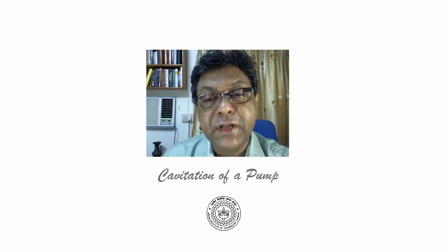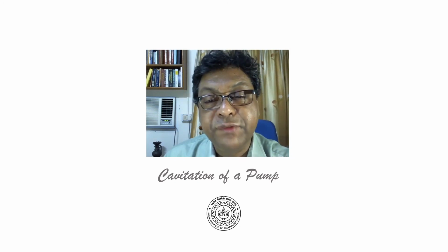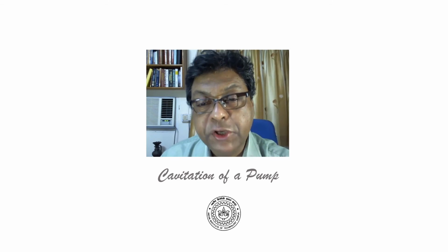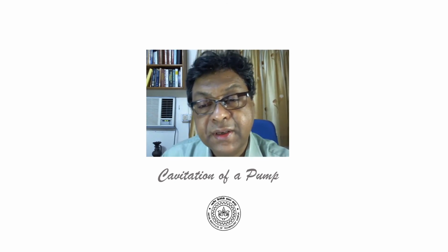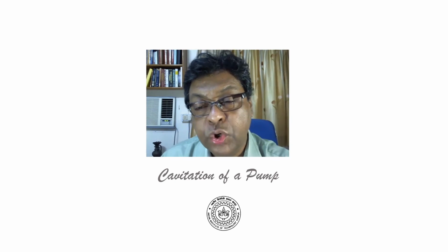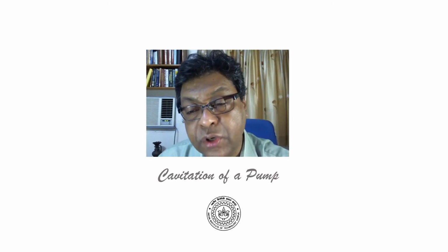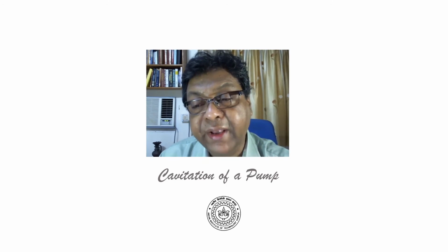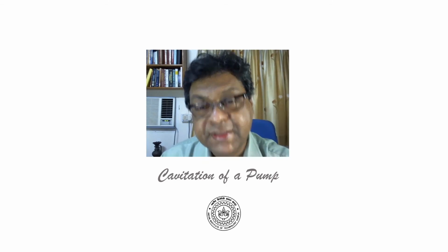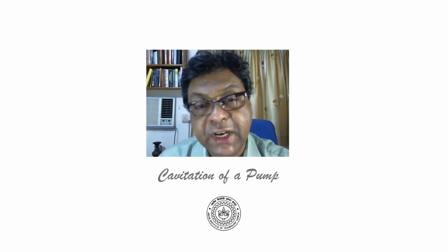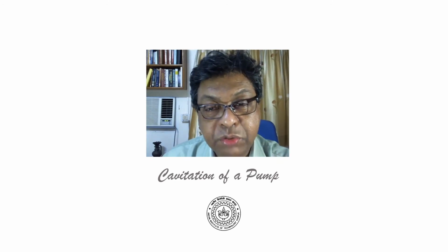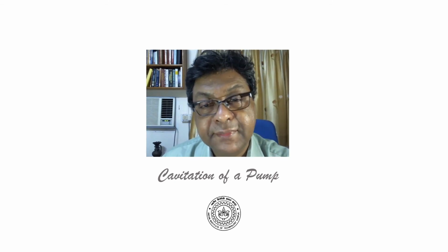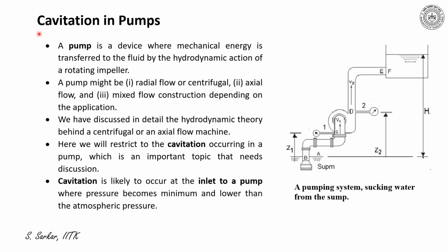I would like to present now the cavitations for a pump impeller. Please note that the cavitation originates on the suction surface at inlet of a pump impeller, while the cavitation occurs at the exit of a turbine. This is a significant difference between a turbine and a pump impeller with respect to cavitations. I will now concentrate on